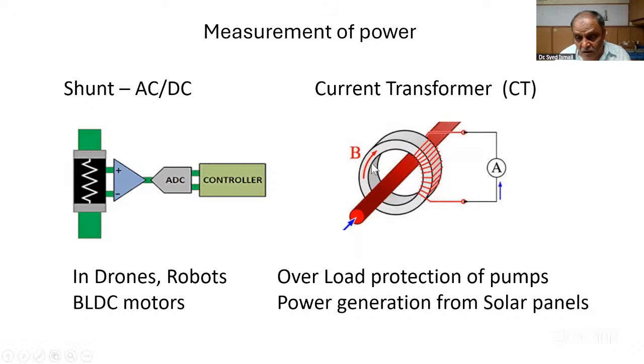And this outside coil, because of the magnetic core, picks up a small amount of electricity. Because electricity is flowing in this direction, some more electricity is generated outside. How much distance between them? Could be 2-3 centimeters also. There's no problem. So it generates a small voltage. You measure this and you know how much current is going. So you relate the current flow in the conductor to a relative voltage generated outside. They are almost linear, and they are available.